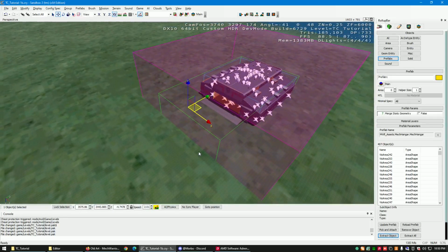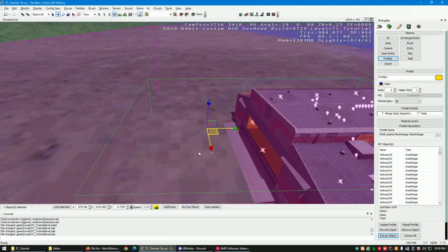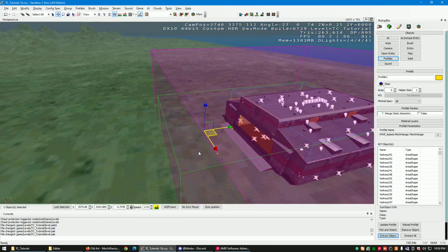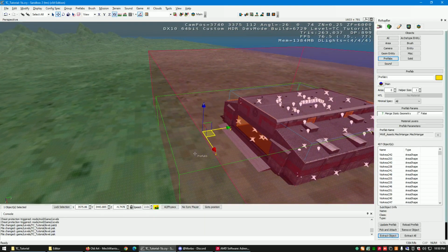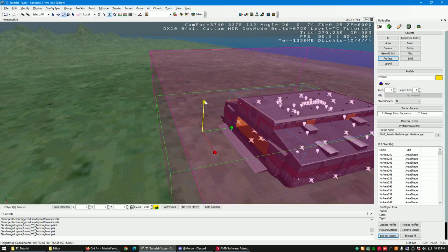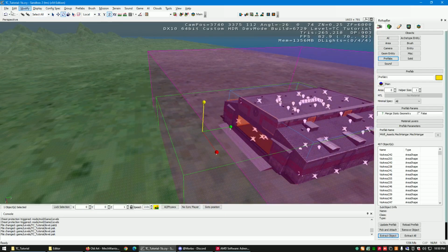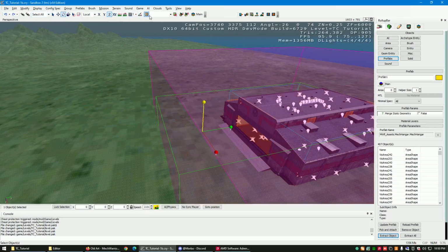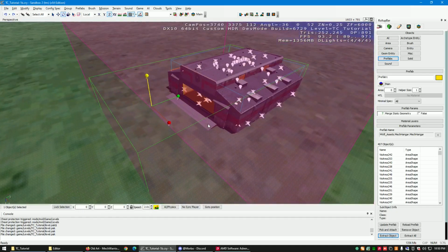Another thing that I find makes it easier to place things is if you keep them rotated at 90-degree angles. So in other words, you have the snap to angle, so that changes it every 5 degrees. If you disable this, it does it every degree. There's no limit to it. If you want to go back, use your undo. I typically keep it on for most cases. Same thing with snap to grid, so it moves it in certain areas.